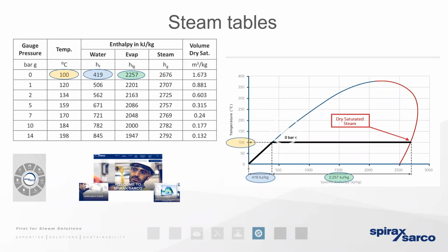But in this particular presentation, we're focusing on steam and heat exchange. So we know that if we've got wet steam, the steam is going to exist with far, far less energy contained within it when it's wet compared to that dry saturated steam. And the problem we have is that the steam tables, which are the basis for sizing and selecting the appropriate heat exchanger for the process, are all based on the assumption that we're getting steam that is 100% dry and therefore with the maximum amount of heat energy present within it.